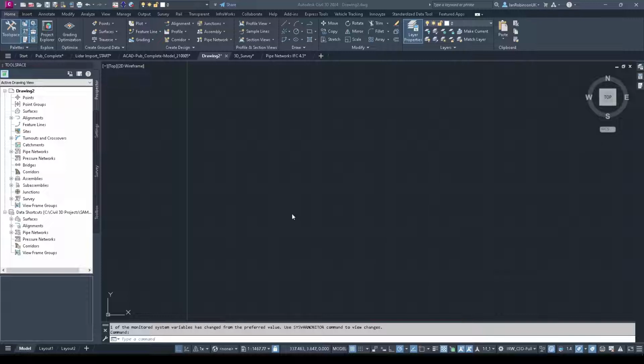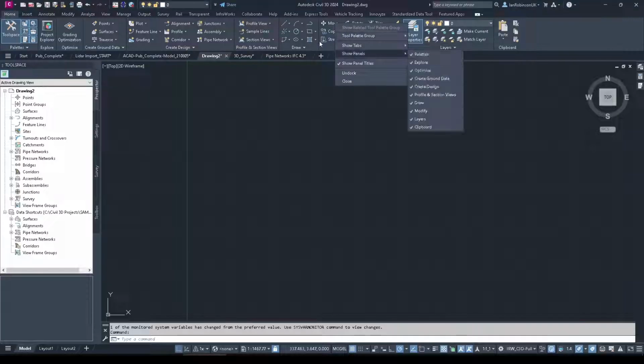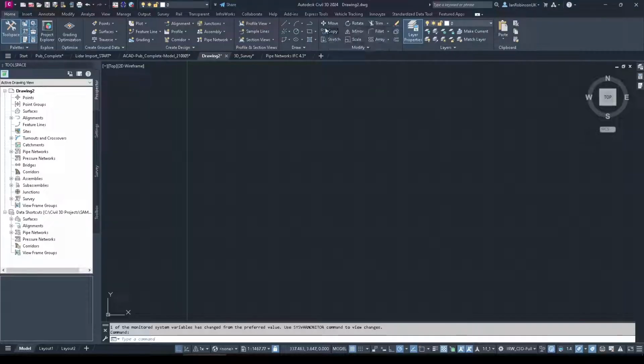Next, again, this is just AutoCAD based. I'll look at a couple of civil ones in a minute. But you can look at using the quick access toolbar a little bit more effectively as well. So that's this thing at the top here. You're probably all aware, if I wanted to add something to the quick access toolbar, I can simply right click and add it to the quick access toolbar, and there it is, and I can use the tool from there, and I can right click and remove it from the quick access toolbar.